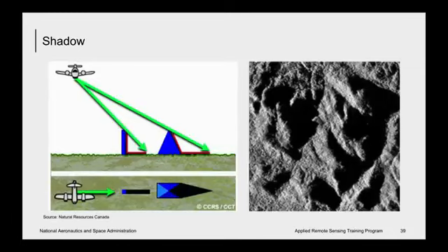As incidence angle increases from near to far range, so will shadow effects, as the radar beam looks more and more obliquely at the surface. The image on the right shows these shadow effects. There are ways to correct for shadows through interpolation. However, I personally prefer to leave the shadow areas as they are, so I consider them data gaps rather than using interpolated values.